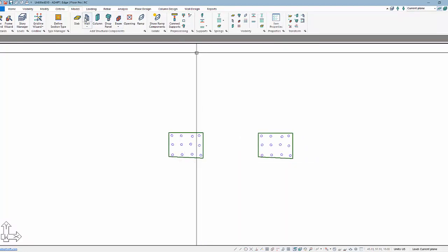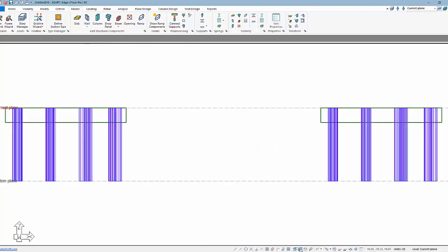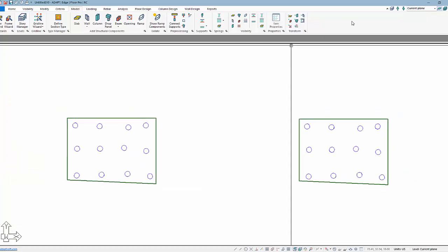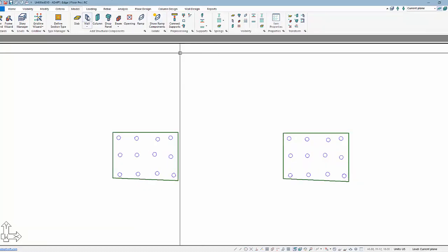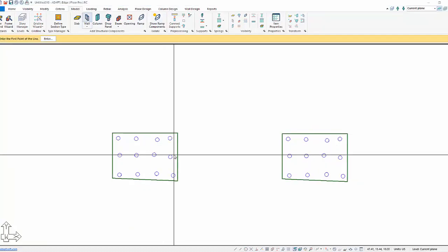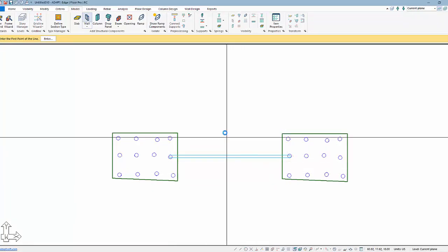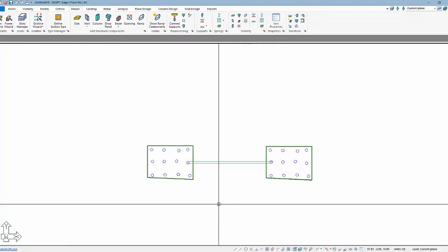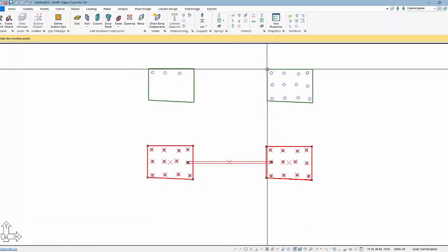So I'm going to model a wall. Now everything is being modeled below the reference plane. So if I go back to the side view, we can see everything is modeled below that. And I can make different elevations or different heights for these stories. Right now everything is set to 10 feet. We'll go ahead now and model a wall. So this is really what we call, maybe consider a grade beam that's carrying multiple levels above it. And I'm going to now take this and just copy this over, let's say to here.